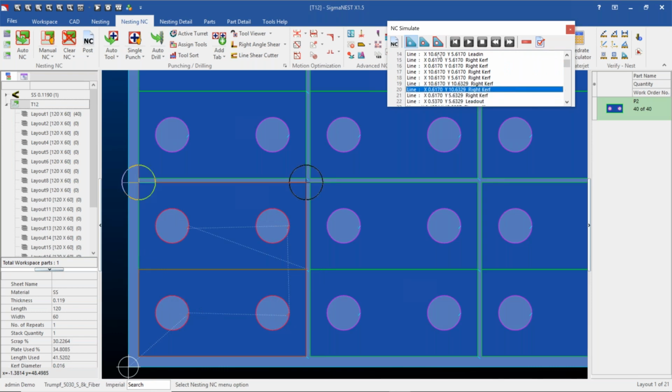This is where we're talking about the pickup points for this location right here, because the first part would actually be finished at that point, and then this is where a pickup point can be introduced so that it extends the cut into that next part, so that if it does tip, your head would be away from it from the previous pickup point.